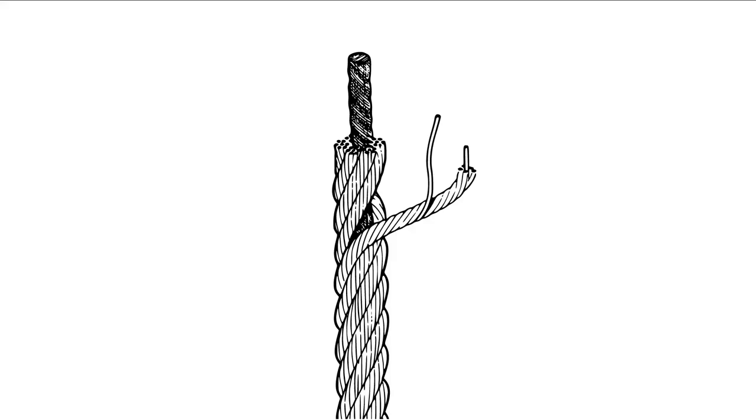The amount of load that can be carried by this arrangement is greater than the yield stress of the cross-section of all of the wires. This is because there is an additional amount of load that would be needed to be applied to pull each wire straight before it is actually loaded completely in tension. Compression and friction acting between each of the wires making up the rope due to their orientation act against this. Furthermore, the entire rope is not deleteriously affected if a single strand breaks. The remaining ends of the wire could still interact with the remaining unbroken wire on the same basis, preventing other wires from aligning with the orientation of a load directed along its length.